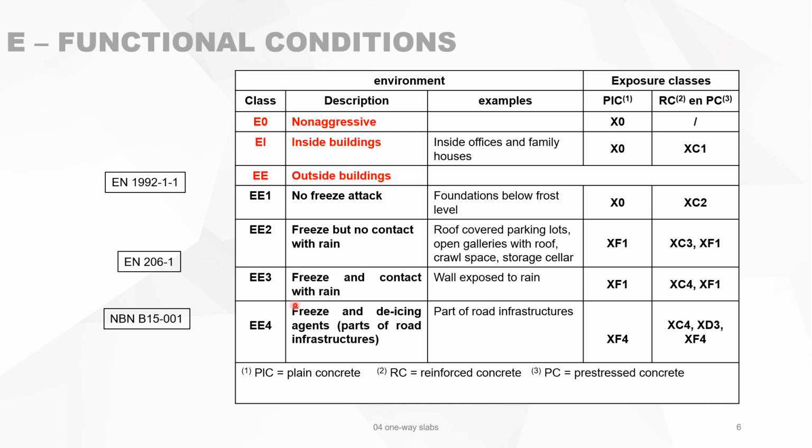Then the third group is freeze and contact with rain. This is a wall, for instance, exposed to rain. And freeze and de-icing agents, part of road infrastructures, is the fourth group, EE4.